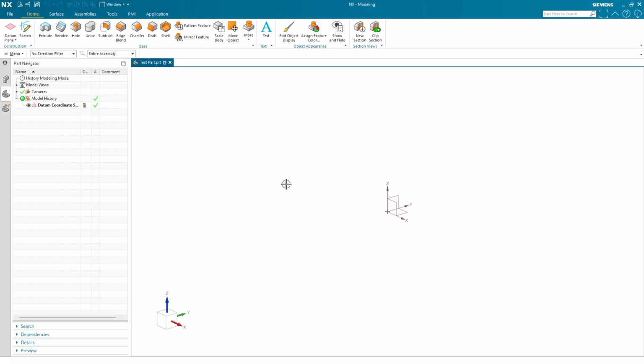We can set work views. So this is pretty useful when it comes to exporting stuff. When you try to export a DXF, for example, like a 2D pattern, it's going to ask you if you possibly want to use the work view to export. So right now it would try to export a DXF projection of my part in the trimetric view, but I can set it to the top, right, left, isometric. It doesn't change the functionality of home and end. Like I still get the same views no matter what my work view is, but it defaults to trimetric.